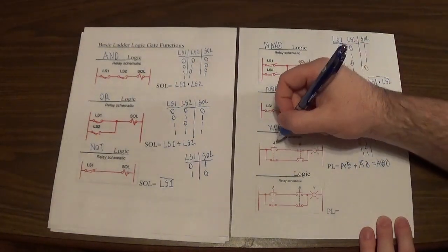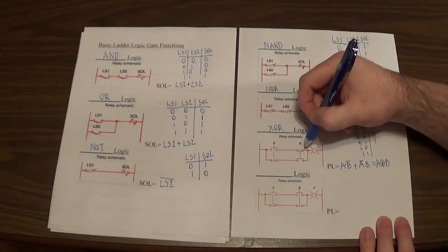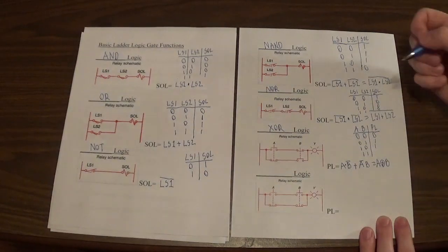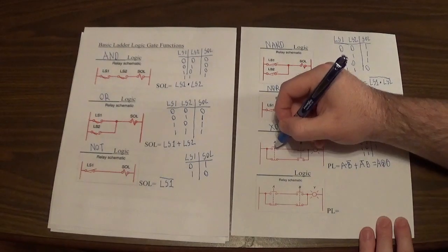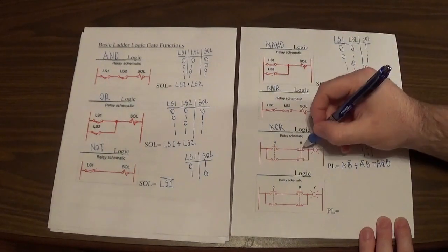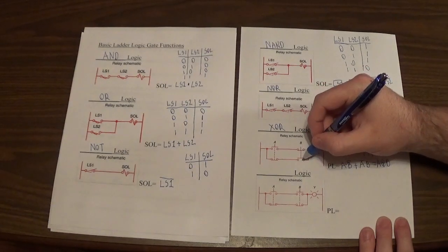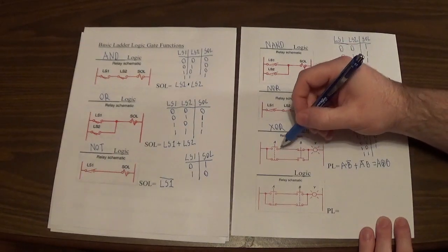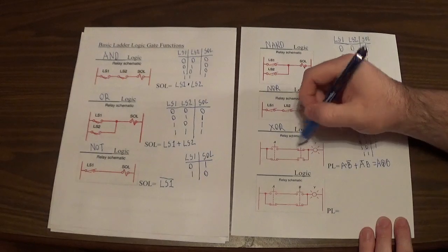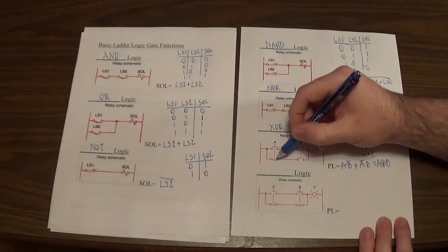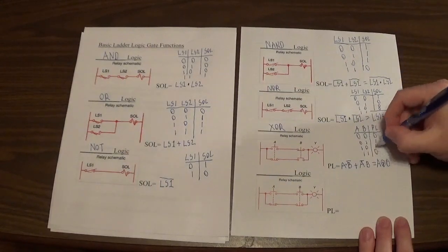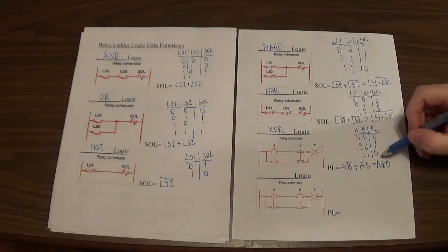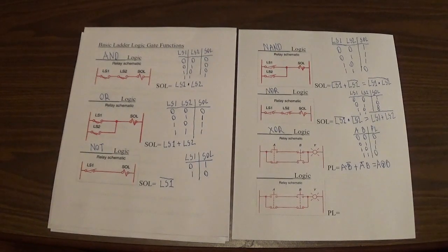If I let go of B and activate only A, this will close, B will remain closed, and the pilot light will be on through the top line. If I push both A and B, A closes up here but opens down here, and B opens up here and closes down here, so it becomes exactly the opposite, so there's no path for current flow. Because this will be closed but that'll be open, so it can't go that way. This will be closed but this one will be open, so it can't flow that way. So that gives us our exclusive OR operation, where like inputs give you a low, unlikes give you a high.